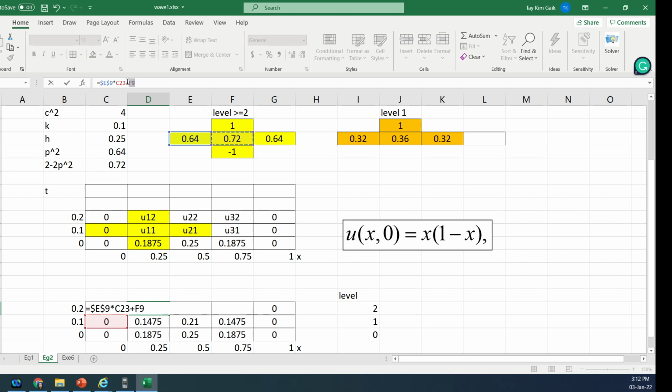Then from where you key in the formula, go down to the middle level left, plus this coefficient, make it constant, multiply from where you key in exactly down one level, same column, plus the coefficient 0.64, constant it, multiply from where you target, which is D22, the right is E, and then go down to 23, so D23. Then minus one time, so minus from where you target D22, one, two, same column, so D24.